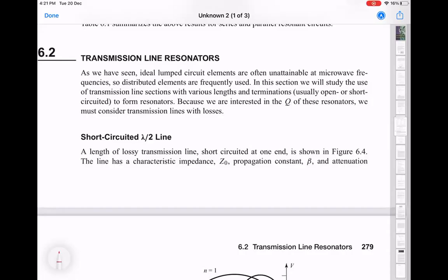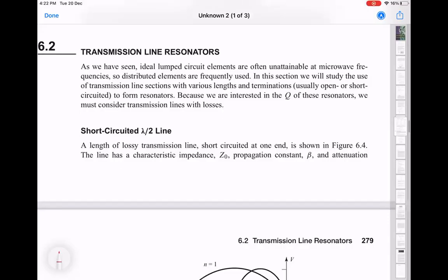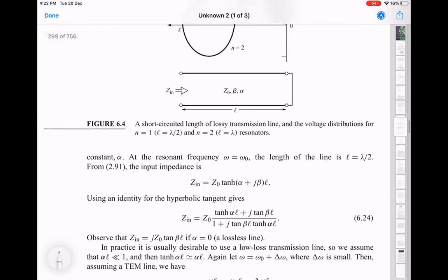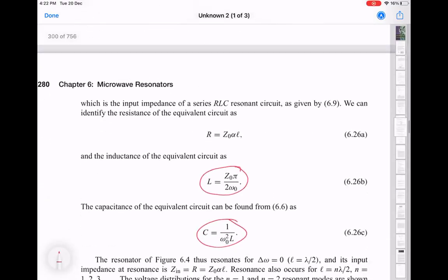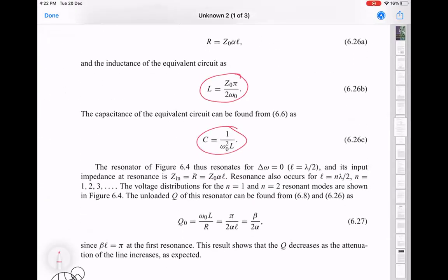And as we were seeing last time, the effective inductance and effective capacitance we get from the model when we convert a transmission line resonator into an equivalent LC oscillator is a perfect one-to-one mapping within the small range of frequencies where we are working. So just reminding you of these kinds of expressions, and then we'll go back to Microwave Office.